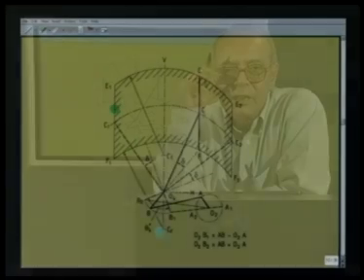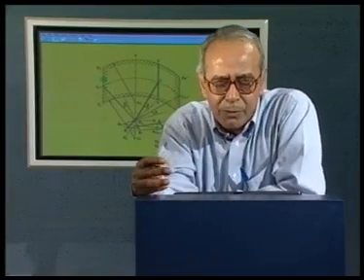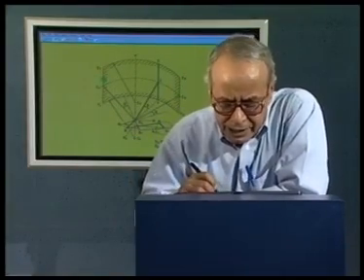So, as a designer, maybe we can make a very little change to make this field of wiping symmetrical about this vertical line. So, the second part of the problem is: retaining all other link parameters the same, change only the angle delta, which was given as 16 degree, to make the field of wiping symmetrical about the line O4V.